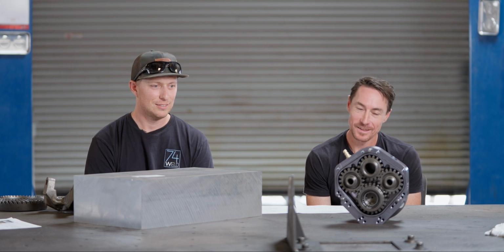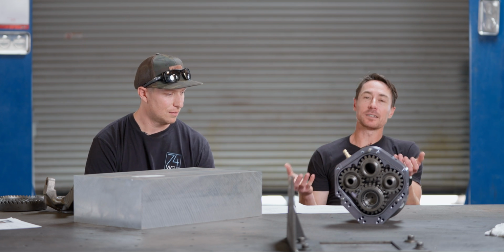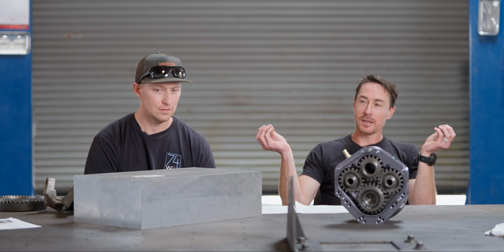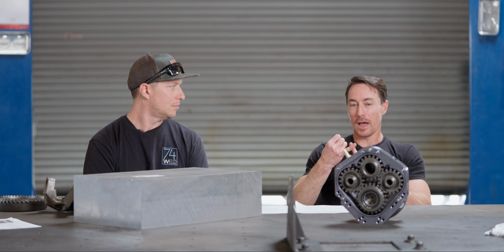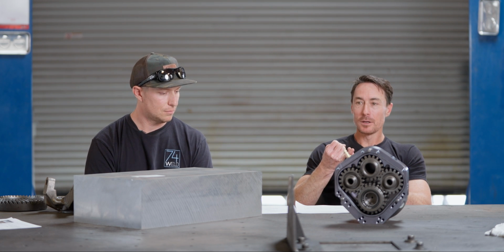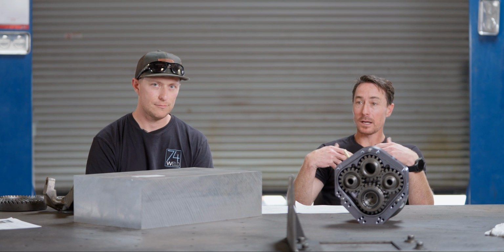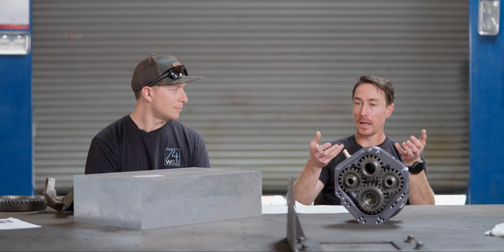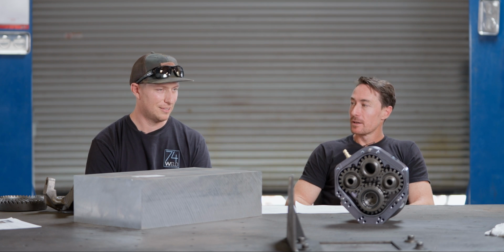And I'll clarify that. Because it's sand cast, you'll get sand embedded in the material, so you can't cut it with carbide. You have to use high-speed steel. And it's very abrasive. So while it cuts really well and it's strong, it's kind of hell on machines.